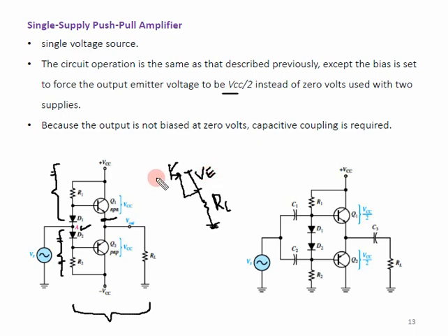And you can prove that. Now remember this thing: this is the diode part, and this is the point A part. This is a transistor, and this is connected to its collector. This is diode D1, and here you have the resistor R1. If this point A has a value of 0 volts, then by KVL we can also prove that VE will be equal to 0. You can prove it using KVL in this loop. So VE is equal to 0.